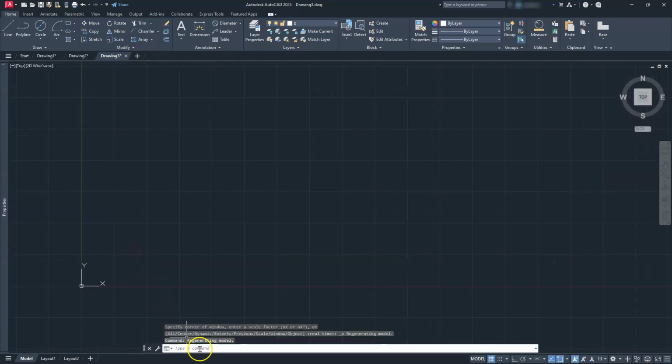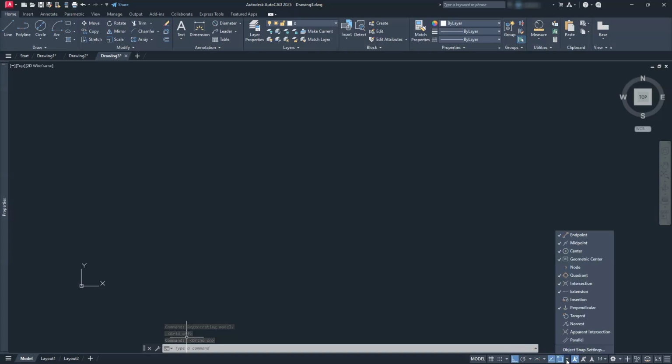Alright, so the normal stuff I usually like to do is go ahead and turn off the grid. I turn my ortho on, and then I'm going to make sure I see what running O-snaps I have on. Now, we can choose to switch over to the 3D portion now, or we can wait a little bit later. And I think I'm going to wait a little bit later.